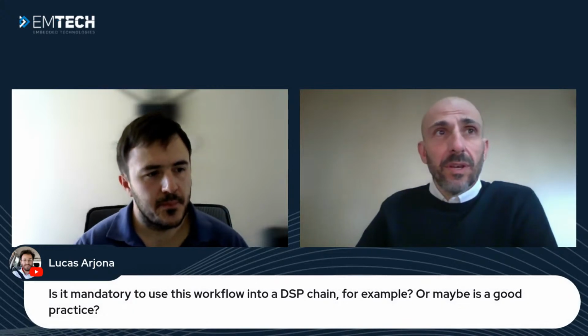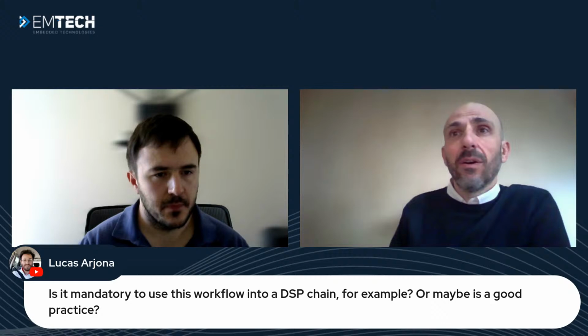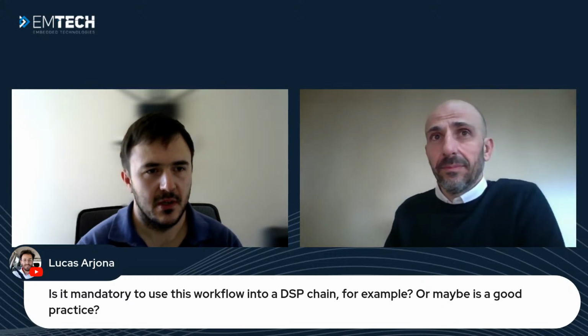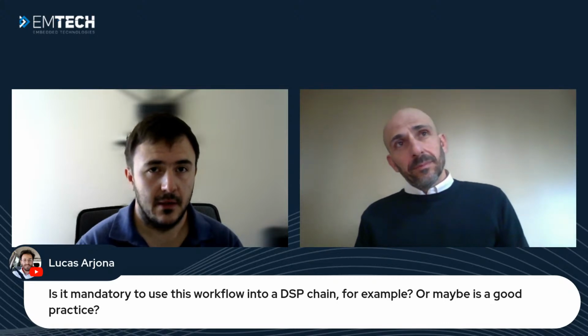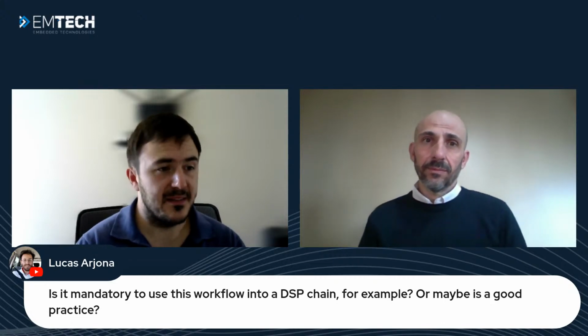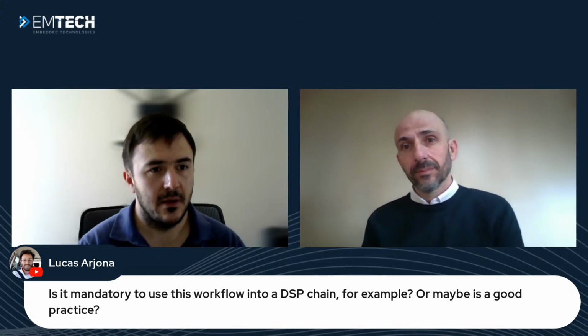Okay, excellent. And we have one last question, which is: is it mandatory to use this workflow in a DSP chain, or maybe it's just good practice? I mean, of course, nothing is mandatory. There's a reason it's been used so much lately. If you have no kind of valid data or valid signal along a DSP chain, you have to balance the latencies pretty much manually along the path.